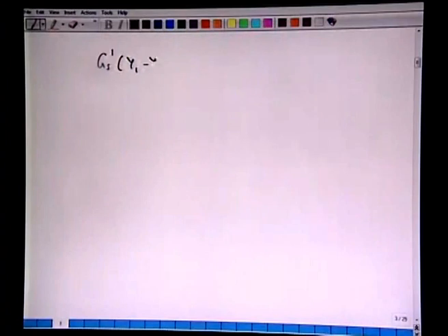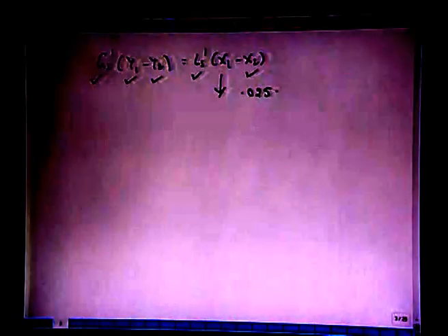Okay. Again, here one can take this curve and write the operating curve expression as GS prime (Y1 minus Y2) equals LS prime (x1 minus x2). GS prime is given to us, Y1, Y2 are known to us. LS prime we know, the operating value is 30 kilomole per hour per meter square. X2 is 0. So, x1 can be solved here to obtain the same as what we obtained graphically, 0.02588.